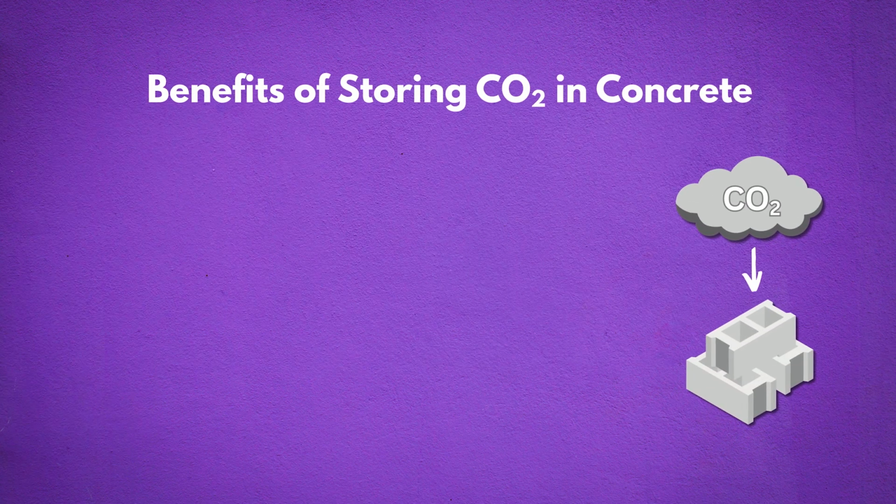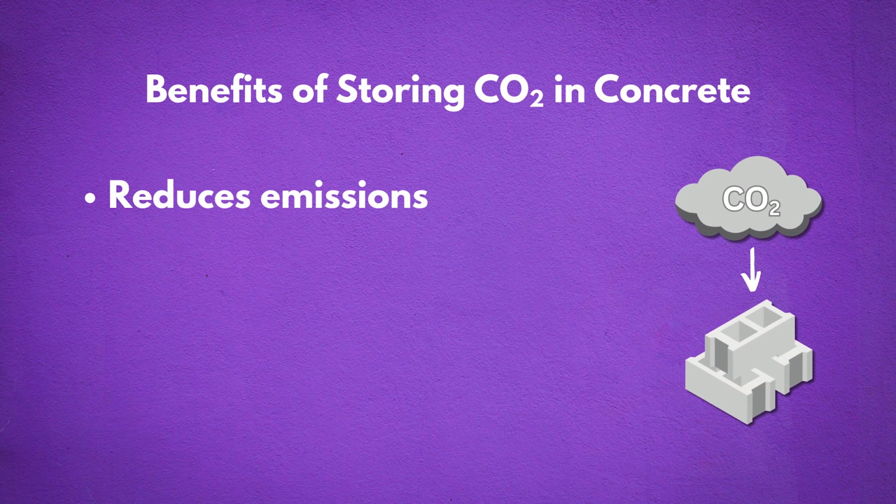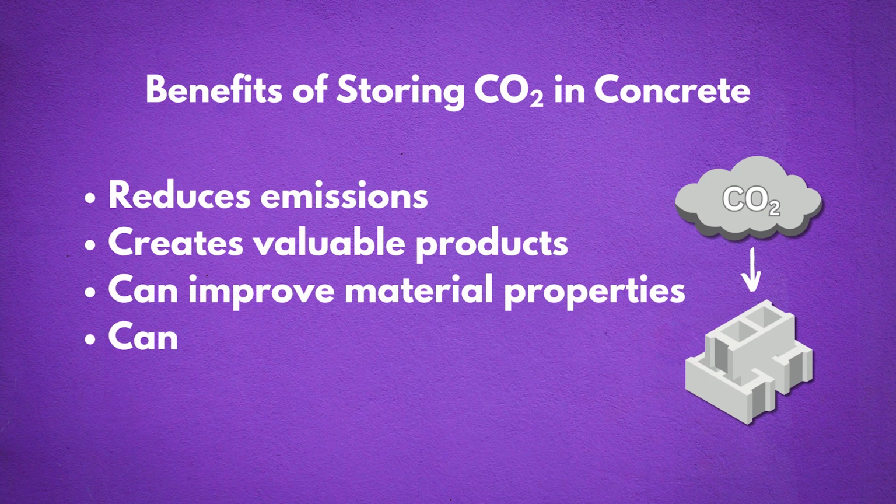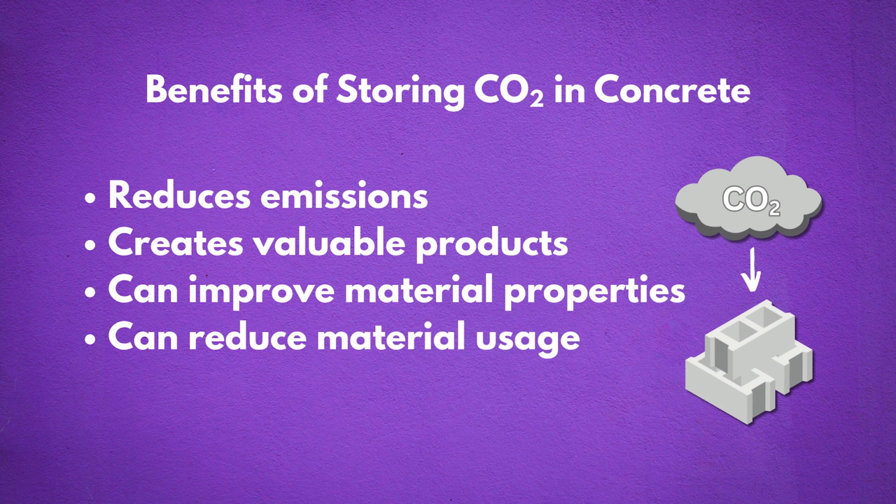Taking CO2 from our atmosphere reduces global warming, offsets the high carbon emissions of concrete production, and creates valuable products. Concrete with carbon dioxide embedded has increased strength, so less can be used for the same application, leading to money savings.